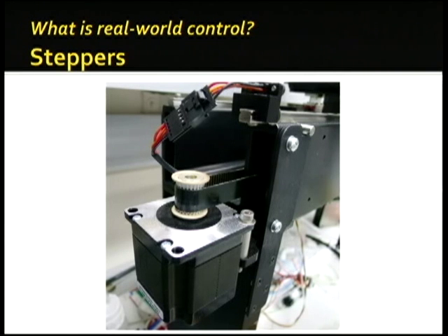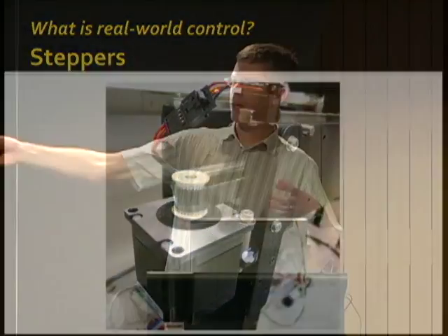And this is just a stepper off one of the robots at work. It's got a belt, a drive belt that it's hooked to. And what that means is you can keep the stepper motor in one position and have that belt driving an axis somewhere else that allows it to whiz up and down a particular axis. You put enough of those together and you start to get X movement, Y-axis movement, Z-axis movement, and you can start to do some very nifty things in 3D space.